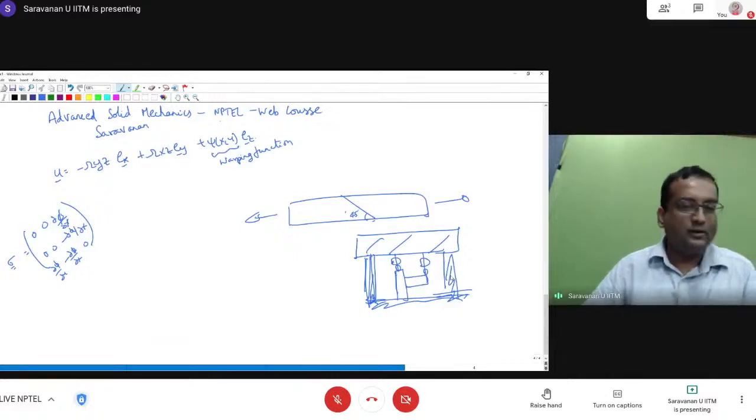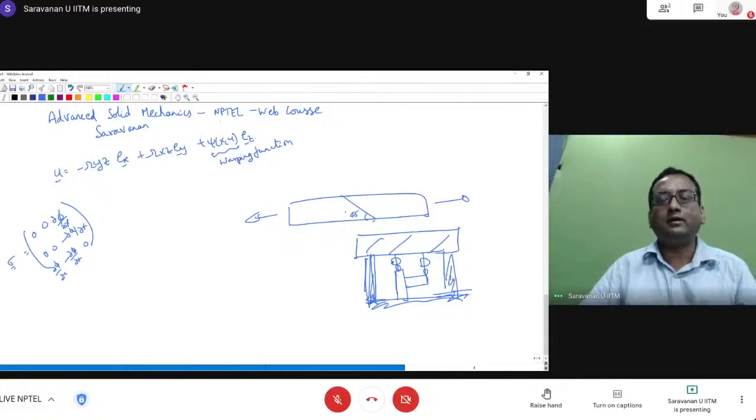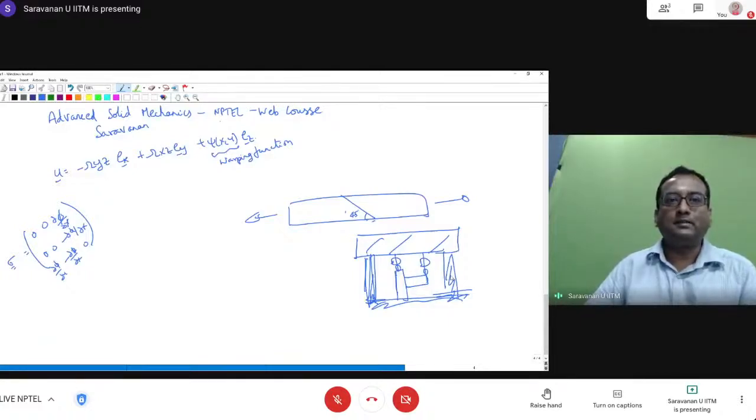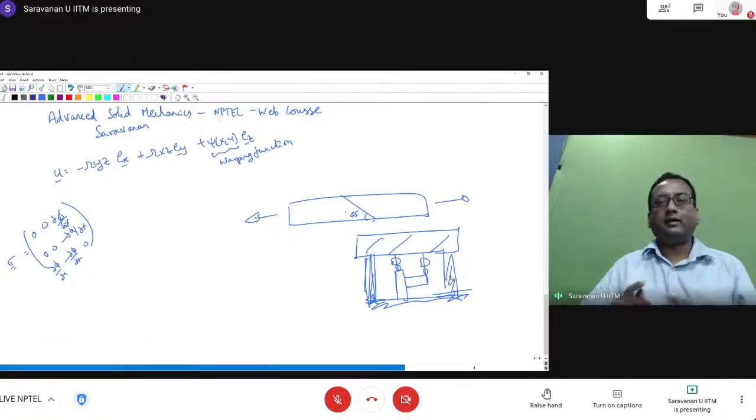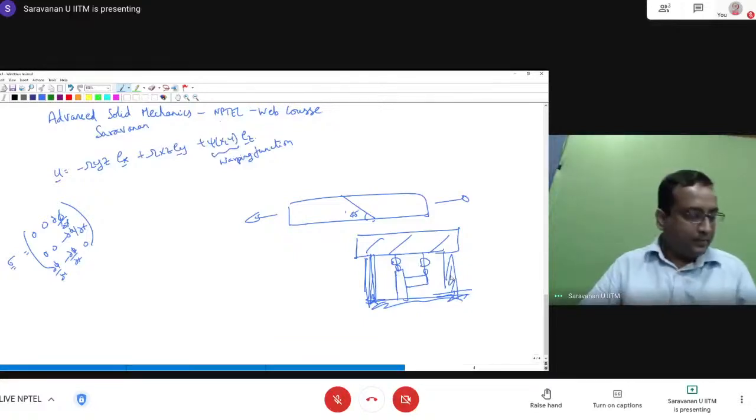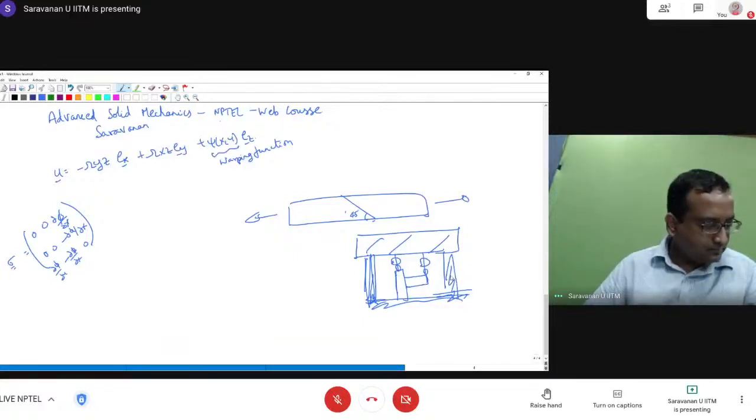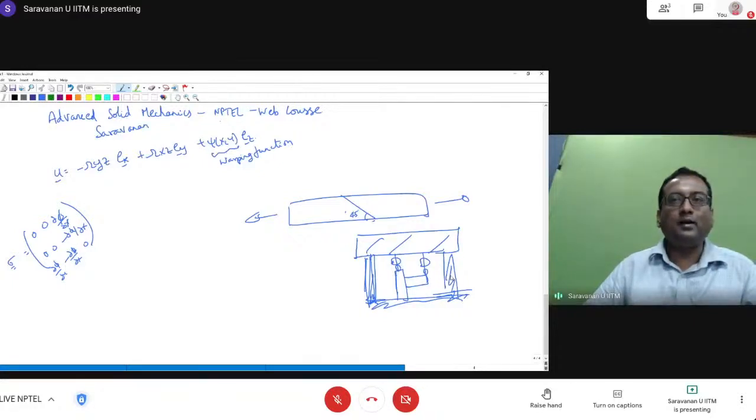Good question. For deriving beam theory, we assume pure bending, which is not satisfied in cases where we apply the formula. Actually, we go out and apply it. That's the versatility of the theory. That's how good the theory is. Even though it is not strictly applicable, it is nearly accurate. Okay, so that's the power of idealization.